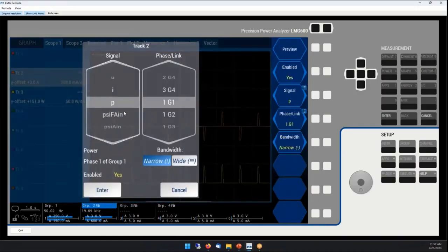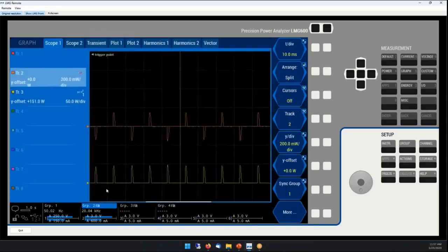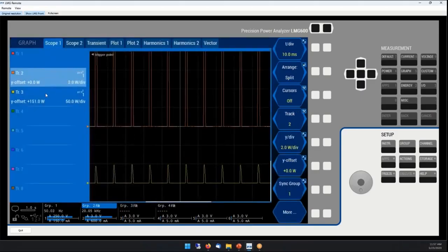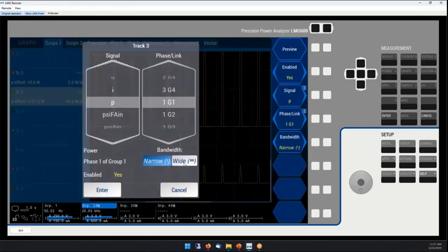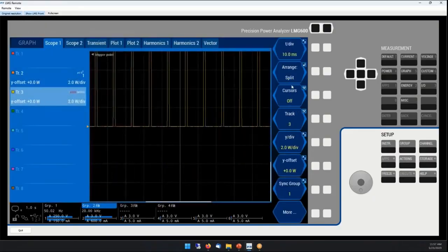Again with the power in narrow band. So here I have two options. Because I have changed the signal processing to dual path, now I am measuring the same signal two times, filtered and unfiltered. So I will take the narrow band signal here. I will change the other one to wide band and see what happens.